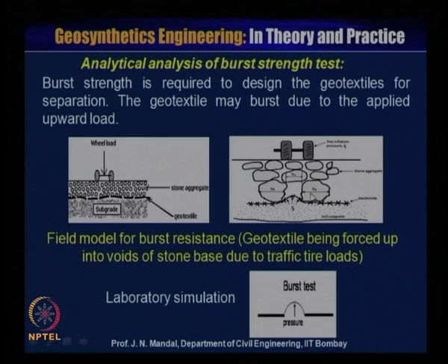So, you can see what is happening in the field, and you can simulate this. Here is the aggregate, here is the aggregate, here is the void between the stones, and due to the application of the wheel load or the tire pressure, this geotextile material pushes into the void of the aggregate, and the geotextile material may burst, which in the field can be simulated in the laboratory.